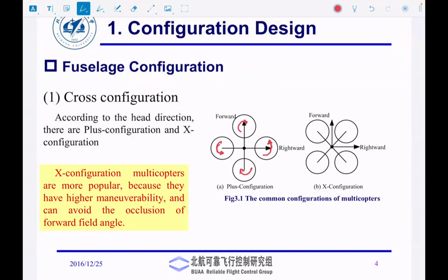Please understand, quadcopters are inherently unstable. Which means unless you have some sort of active control system, that is the closed loop controlling the speeds of the motor, if you just put 4 motors together and run them at even constant speed, you would think, hey, that quadcopter should take off. No, it will not. Basically, you have a control system that is monitoring the roll, pitch, yaw, and then making fine changes to the rotor speeds so that the quadcopter is stable.